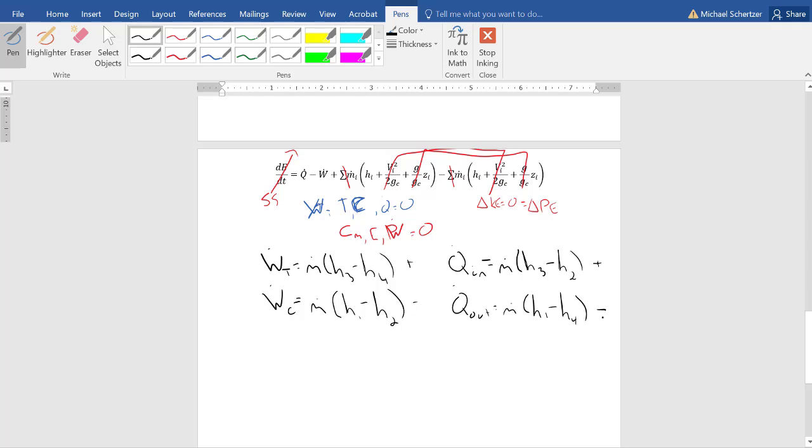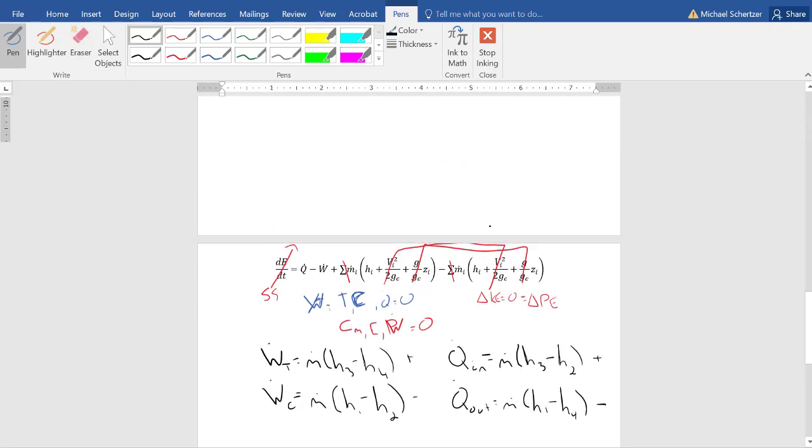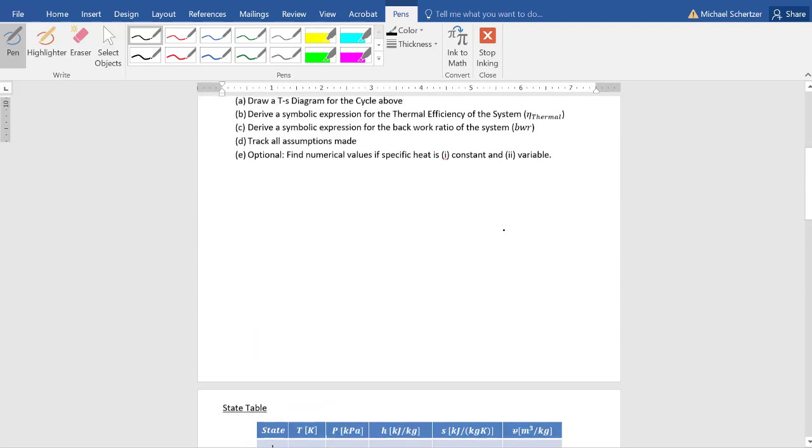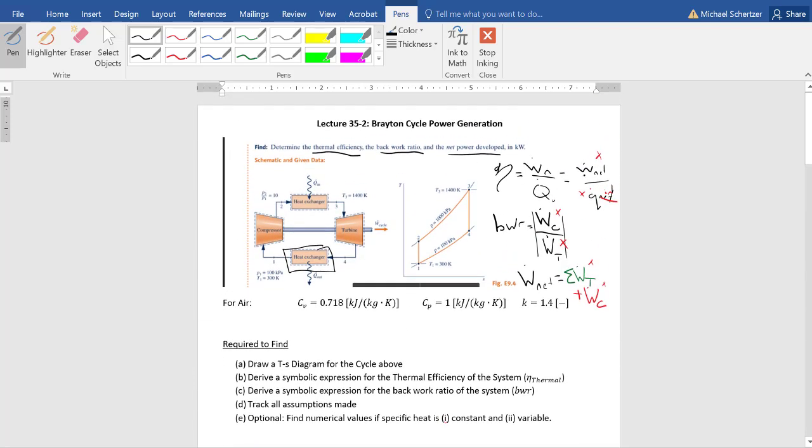So now there's a couple of things, right? If I put these back into my equations that I have up here, then the mass flow rates are going to drop, because all of these components are one inlet and one outlet, and they're all chained together in series. So the inlet for the compressor is the outlet from this heat exchanger called the environment. As we keep going through, there's really only one mass flow rate in this whole problem.